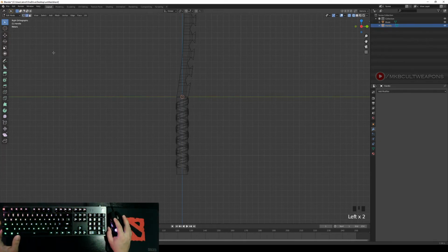And let us go to edge selection, press B, and just select everything underneath, then press G. Okay, that's not gonna work because the proportional editing is not yet ready, so we're going to have to press that button there, or press O on your keyboard, then press G.